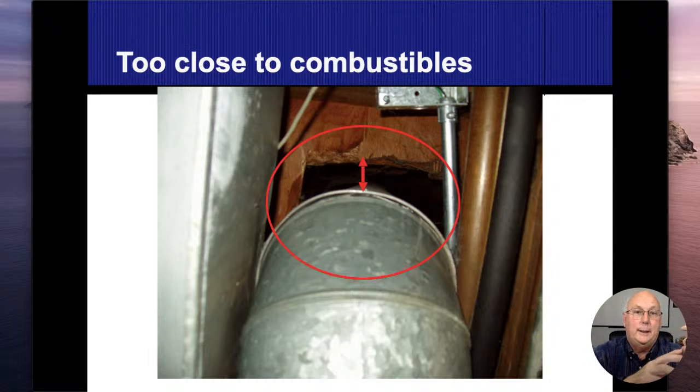And then they also had their air conditioning refrigerant lines touching the vent connector, and that styrofoam insulation, basically this stuff over here on the right, was scorched and melted as well. All right. Now, I hear the argument saying that, well, 6 inches is kind of overkill. I've seen so many times where things are closer than the 6 inches, and never has a problem really occurred.